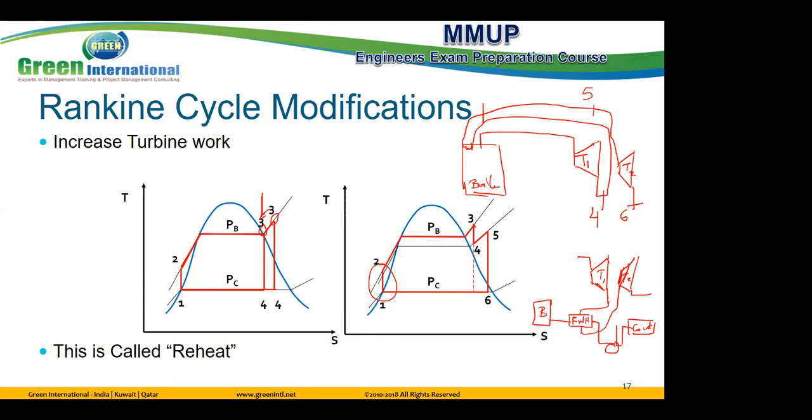For example, we can use 6 stages of turbine, and among these 6 stages, intermediate between them, one goes to reheat and then regeneration and then reheat and so on, making a combination of these by software to obtain the optimum solution, the maximum efficiency, and turbine work also. These are the two main advantages of the Rankine cycle. Efficiency is high, turbine work is high.